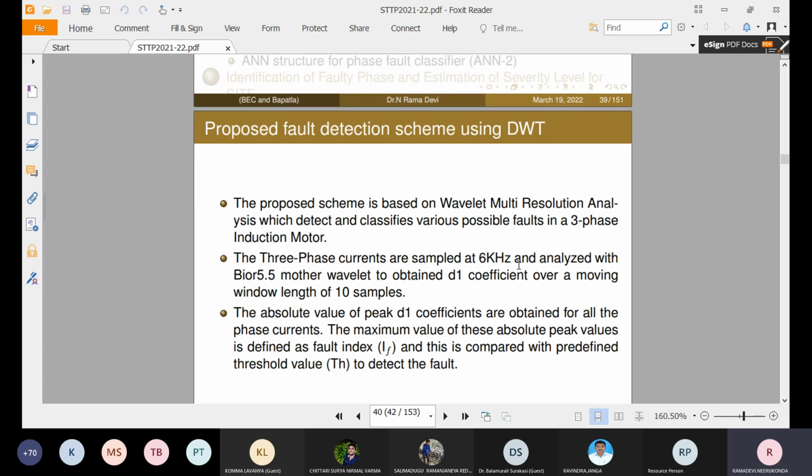In case of vibration signal or temperature measurement, we need sensors placed either inside the frame of the induction motor or outside the frame. But three-phase current measurement does not need any disturbance or obstruction to the motor frame. That's why we call it a non-invasive measurement technique.